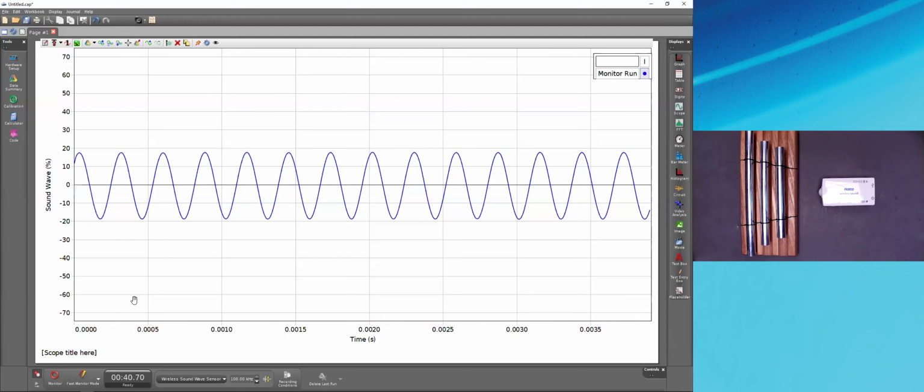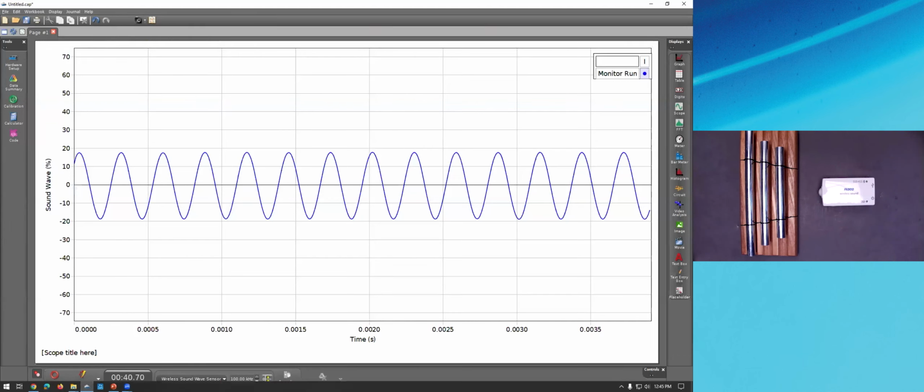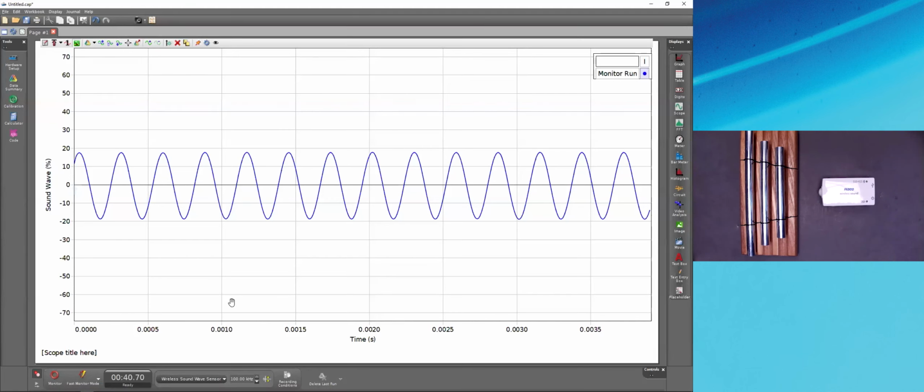Well, how is the scope doing this? How is it accomplishing a sample rate of 100 kilohertz? Well, unlike the continuous sampling mode, it wasn't recording all of the data. It was merely asking the sensor for data at a very high sample rate, as much as could be fed to fill the frame of the scope. So basically one trace, and then it would ask for another one, and it didn't care about losing data between those different frames of data.